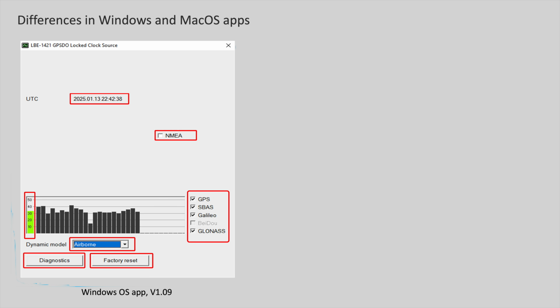That might be interesting if you're using some legacy devices that want this as a serial RS-232 bit stream. Mind you, by the way, that is a 3.3 volt signal, and depending on the other device you might need to do some signal level adaptation. But yeah, it provides some flexibility. It's nice that it's there.